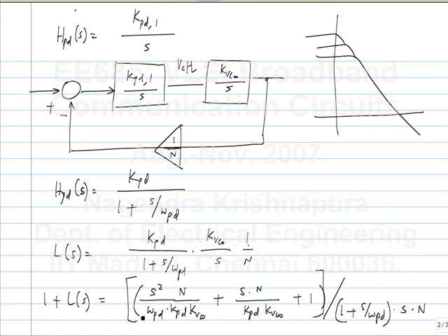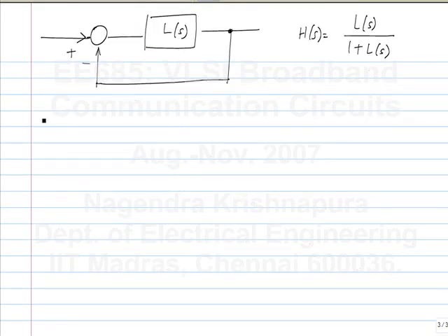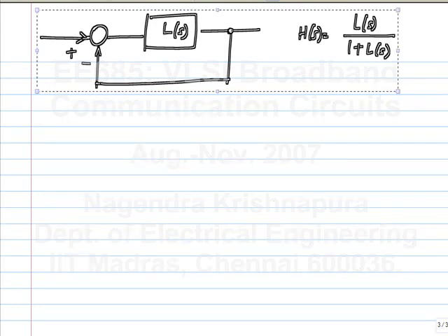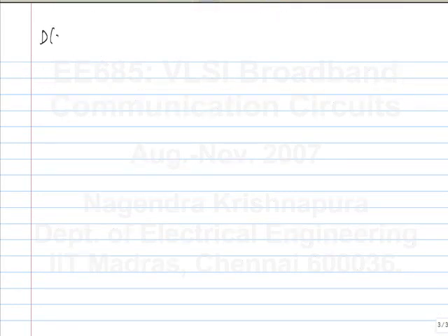But what is of interest is also not whether it is just stable or not, but also how close it is to instability, right? And that is characterized by the quality factor of the system. If you have a very high quality factor, there will be a lot of ringing. That means a small disturbance will induce disturbances in the system that last a very long time. That is also a kind of instability. I mean, it's not unstable, but it is close to being unstable. So, the denominator polynomial for this system.